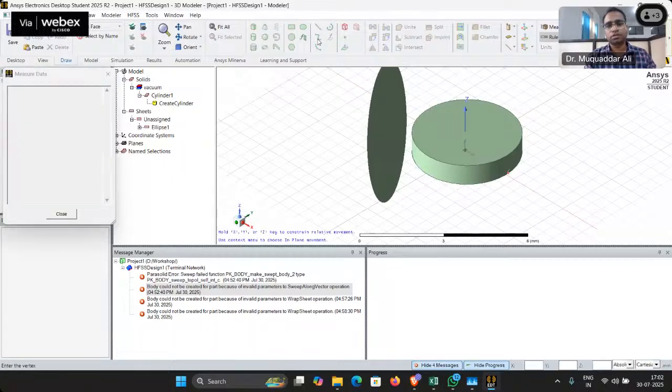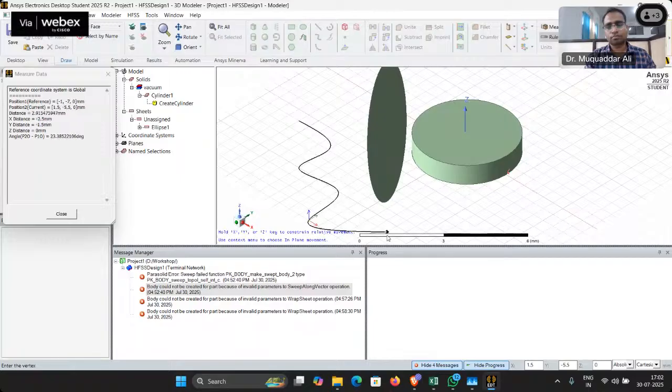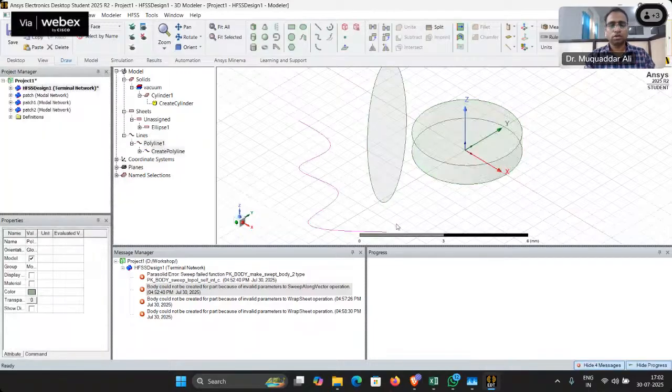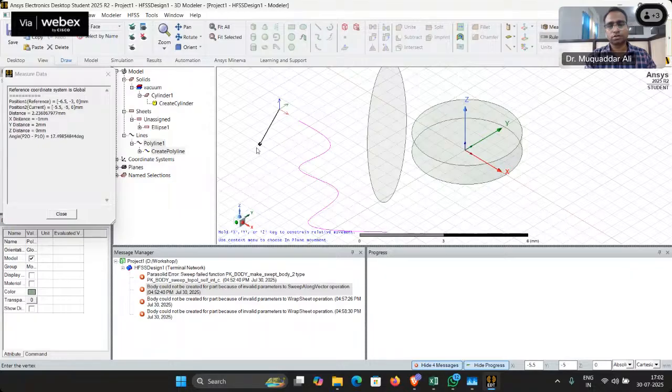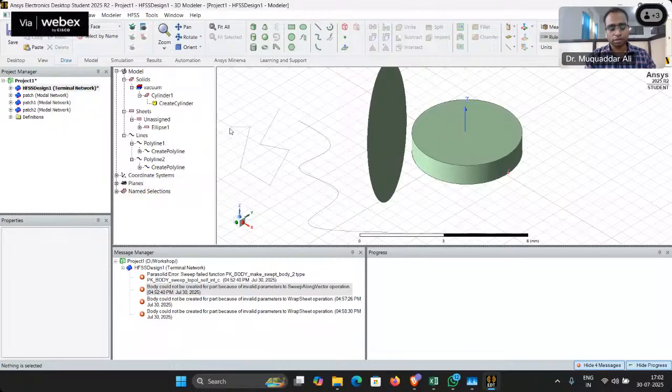So in one dimension, select this line. I'm creating a sinusoidal variation. Whenever you first select this object and click, it will start counting. Then you just click and it will add new points. Now when you want to finish, you have to double click.